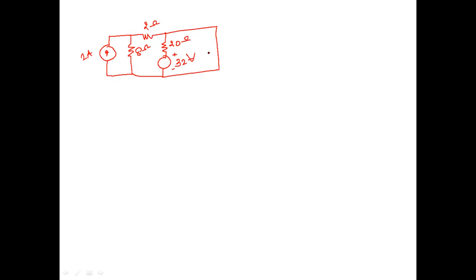And RTh, whatever we have calculated using Thevenin theorem, will remain the same, and is also equal to the Norton resistance, called Rn. Whatever method we adopted for Thevenin theorem, the Norton resistance is the same. But in Thevenin it was opened, and in Norton it is shorted.